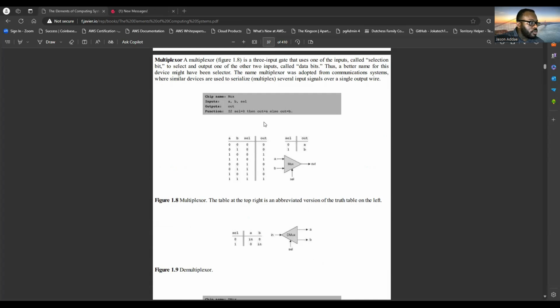And here you have what's called a multiplexer. The multiplexer takes in those 2 input bits and then has a selector bit. The selector is manipulated to be either a 0 or 1 by you. That'll alter what happens to the input. So then you'll have an output of either 0 or 1 based on what the selector bit is. The selector bit is activated, being that it's a 3 input gate.